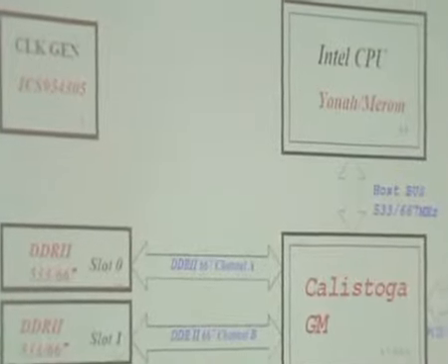We'll go back to page number 4. So this signal comes from the clock generator. Go back to page number 3. In page number 3, see CLK, CPU, BCLK. This signal is coming from the clock generator. So the clock generator will issue a signal CLK, CPU, BCLK. Similarly, this signal is going to the MCH, that is GMCH. This clock generator will issue similar signals to the GMCH, to the ICH, everything. Let's go back to page number 4.